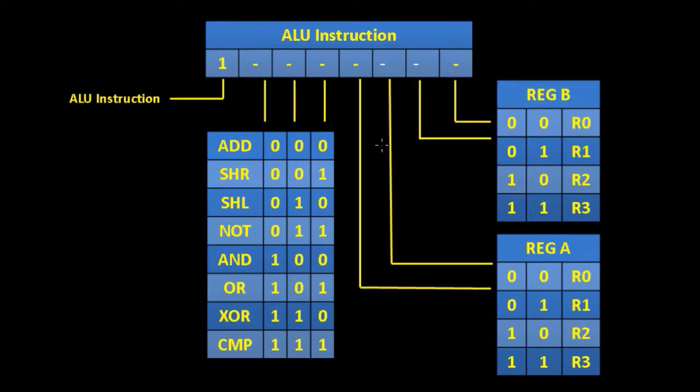So don't worry if you don't understand everything that's happening here on this page, because we're going to take the information that we have here and build it physically inside the control unit. So what we have here is 8 bits, and these 8 bits go into our control unit and control all of the logic which we've still to build, which switches all of the sets and enables.